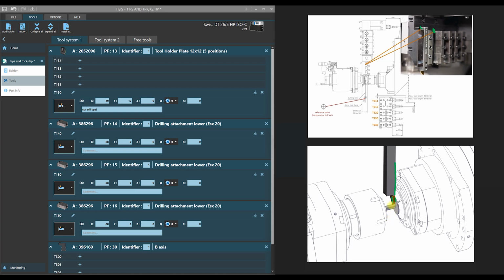determine the geometry of the cutoff tool in Z-axis, we take the distance from this left edge, this edge, to the bottom of a slot or to the surface, this side of the insert holder. In our case, it will be the width of the insert taken with minus sign. Why minus? Because Z1 axis has direction plus here and minus in this direction.